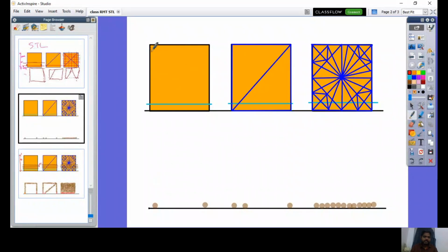only edges and the surfaces connecting the edges. So when I slice the CAD model into n number of layers, you can see the intersection at each layer. For example, the blue line is a plane. It is a virtual plane, because all this activity is performed in software, not a physical slicing or cutting operation. So virtually, the CAD model will be sliced in software. The slicing is done in such a way that it creates an imaginary plane which is parallel to the table or bottom edge, and this plane intersects the edges of the component.